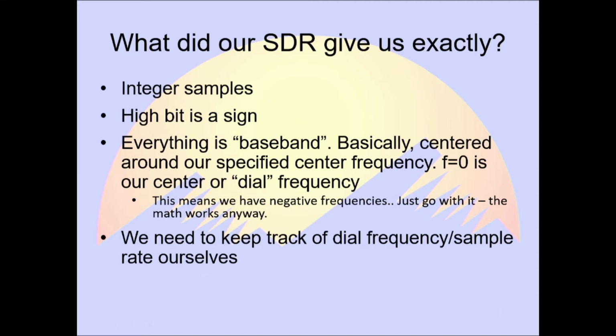Of course, since 0 is the center frequency, we now have negative frequencies, which are not really a thing. This is where the imaginary numbers come in. Kind of a just go with it situation. Don't think too much about the physics. It does make the math work really well, though. We do need to keep track of all this ourselves. The SDR just gives us a big list of numbers.